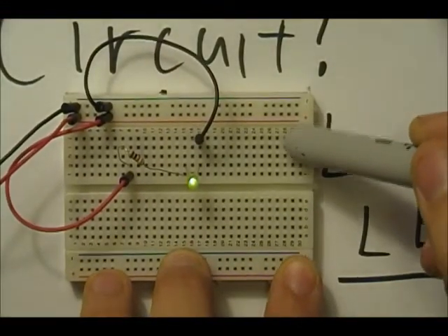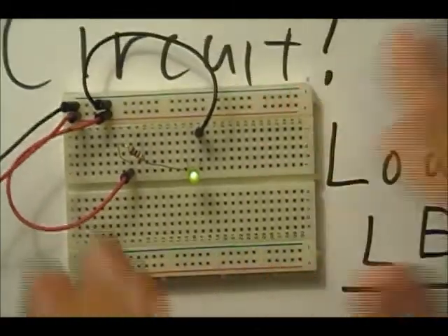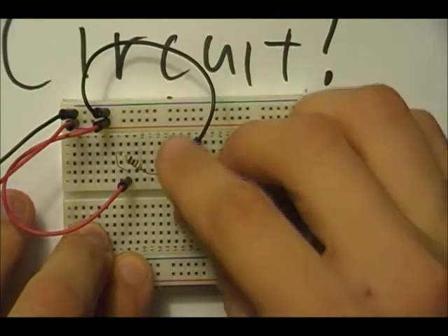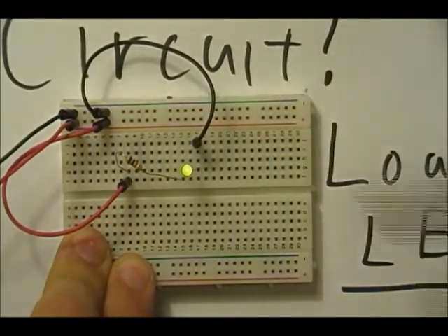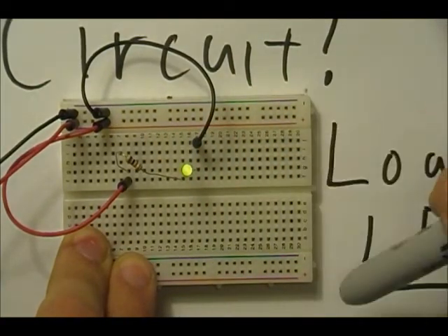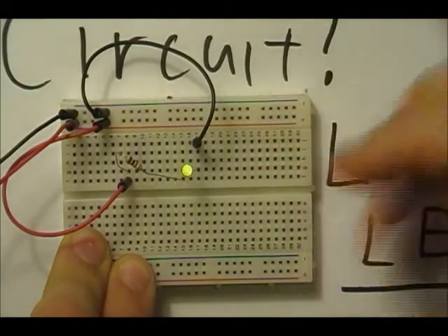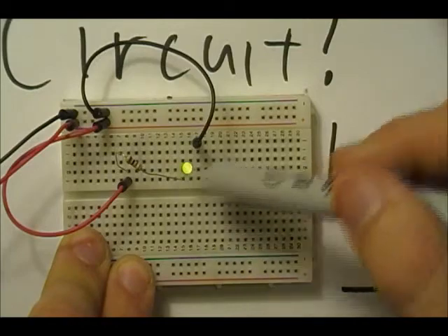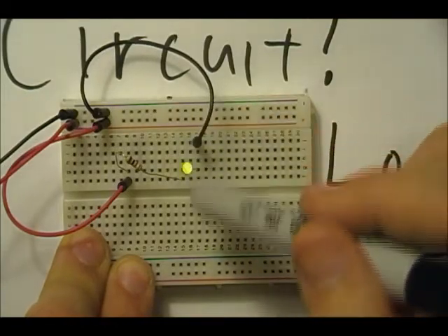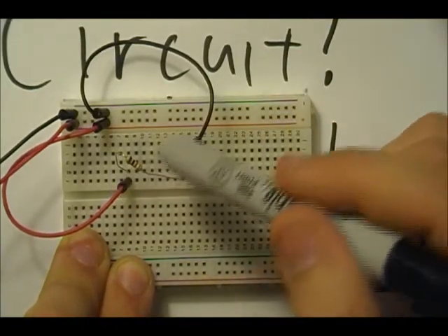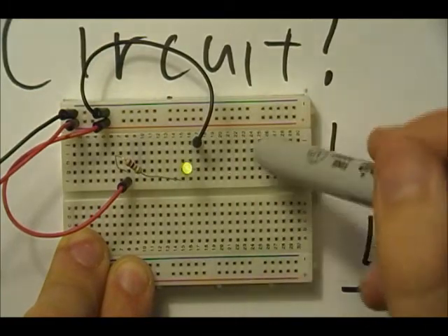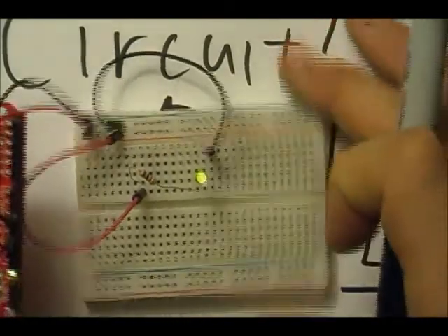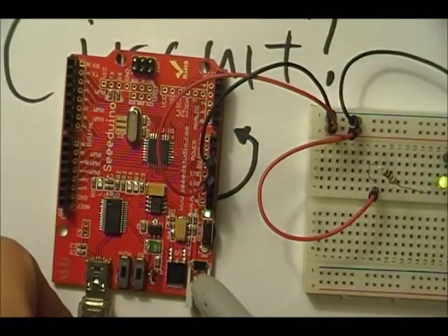Breadboards can electrically connect things because they squeeze onto your components, making it so that they are electrically connected. And in rows like this, they're all together. So there's electrical connectivity from this side of this light and this wire. And this wire connects electronically to this one, even though they're not touching, because there's little bits of metal in the breadboard.